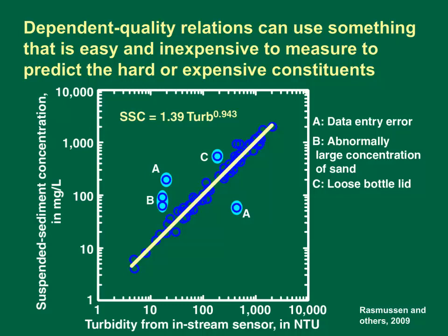The dark blue circles are the data points, and the yellow line is a regression relation that was developed with the logarithms of data. Using the logarithms of data linearizes the relation, normalizes the random variation, and prevents generation of negative concentrations. The light blue data points are values that were flagged as having problems. These data are not used to estimate the line or the random variation. Flow-weighted event mean concentrations for turbidity can be calculated from real-time data. SELDM can model turbidity from the event mean concentration statistics calculated by using the real-time data and can model SSC by using the relation with random variation.